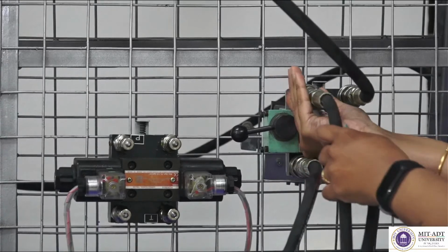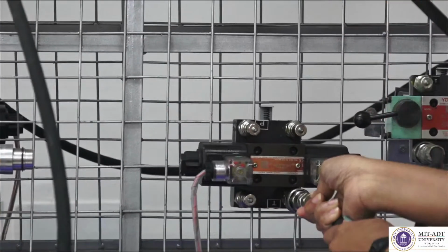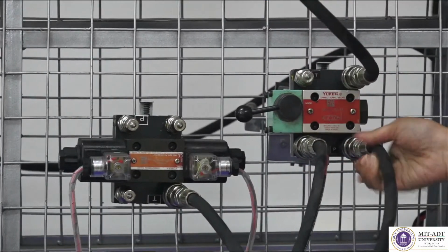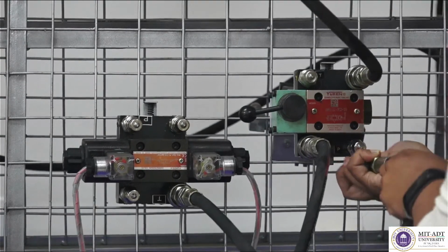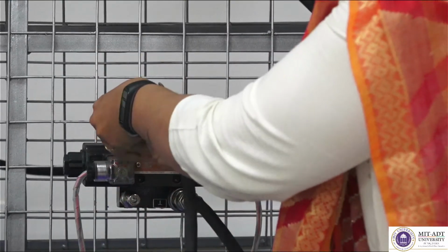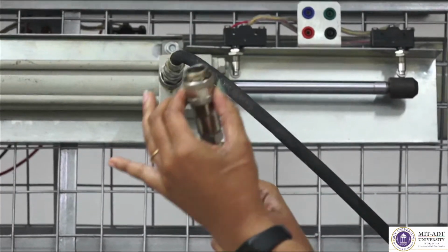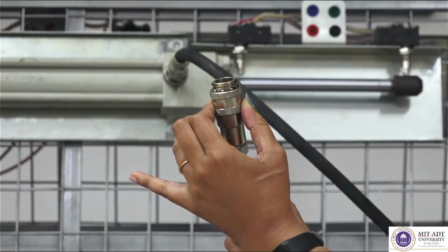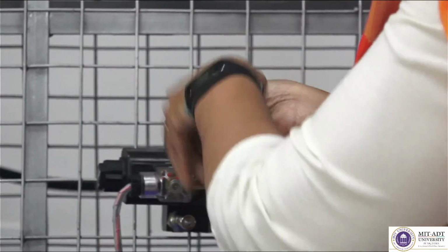This is a tank port. So, I am connecting this tank port towards the tank port of this DCV. It is a press fit connection, as this press fit connection will ensure that the leakage of your hydraulic system would be very less. Here there is a pressurized port. So, I am removing the connection from here and pressing it over here. If you want to see, you can see over here I am pressing it. Here you can see that there are some ball bearings. With the help of these ball bearings, the leakage would be minimum. Okay. So, I am pressing it towards our port P.